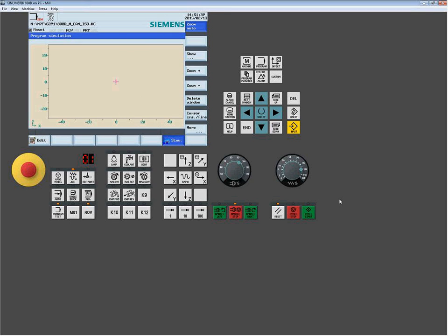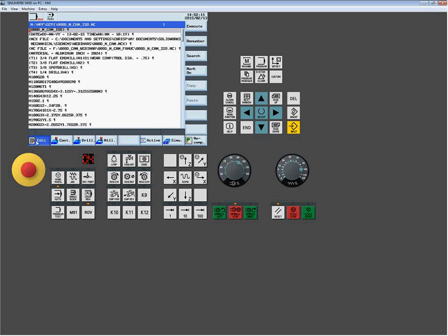Okay, so I come in, cycle start, put in our mode, and now see our fluid sweeping arc. With ISO-based programs, when I'm putting on cutter comp, I've already compensated for the tool. I do need to set my tool radiuses at 0, or I'll get double compensation, just like we saw over on the other side. Now, as well, program exactly the same in either mode.